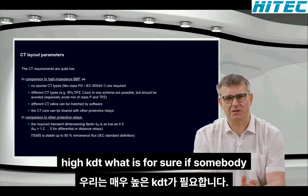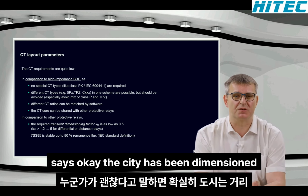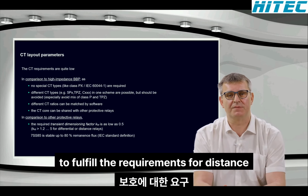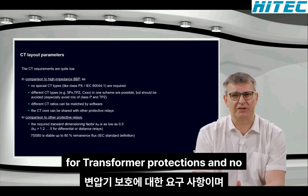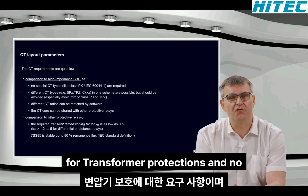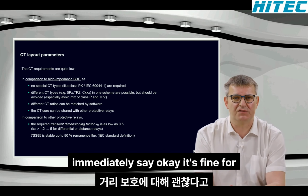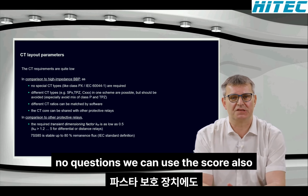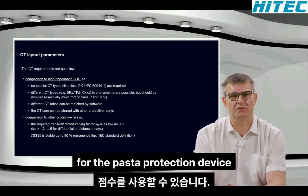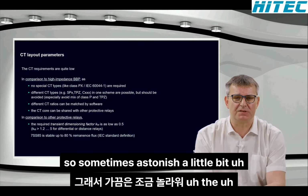What is for sure: if somebody says the CT has been dimensioned to fulfill the requirements for distance protection or for transformer protection, then no further calculation is necessary. You can immediately say, okay, it's fine for distance protection, no questions. We can use this core also for the busbar protection device. This sometimes astonishes a little bit.